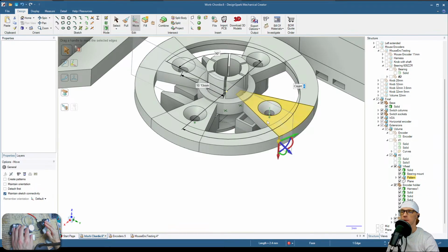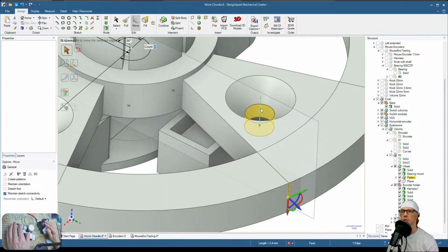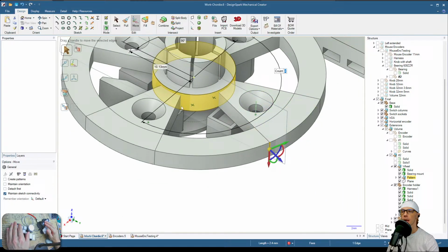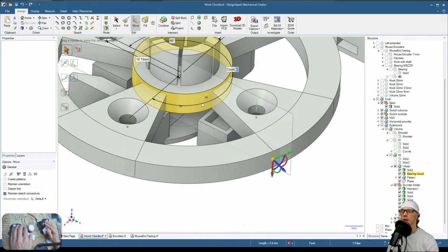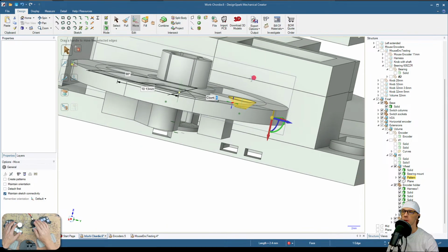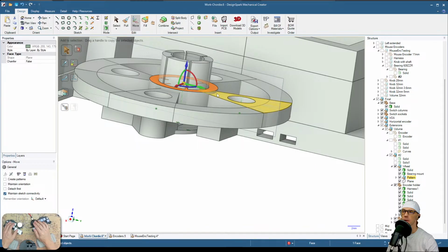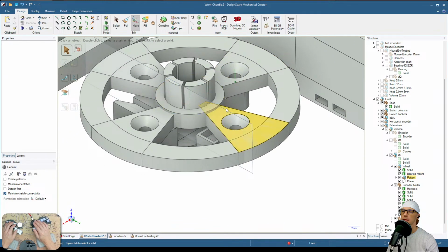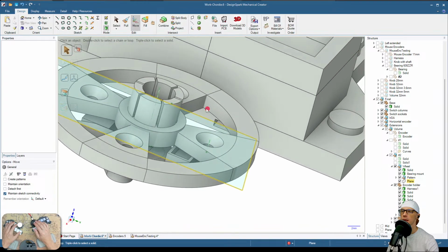Okay, we need to check that, because at 2.4 we have good spacing for the screws, enough to put the screw in and to bevel the edge, so we can hide the head of the screw. Even so, there should be some space because the bearing will be resting on this, and this is 0.4. So it should be more or less enough space so that the bearing won't really hit. That should be okay, but we can always try 1.2 later. Maybe this will change something.